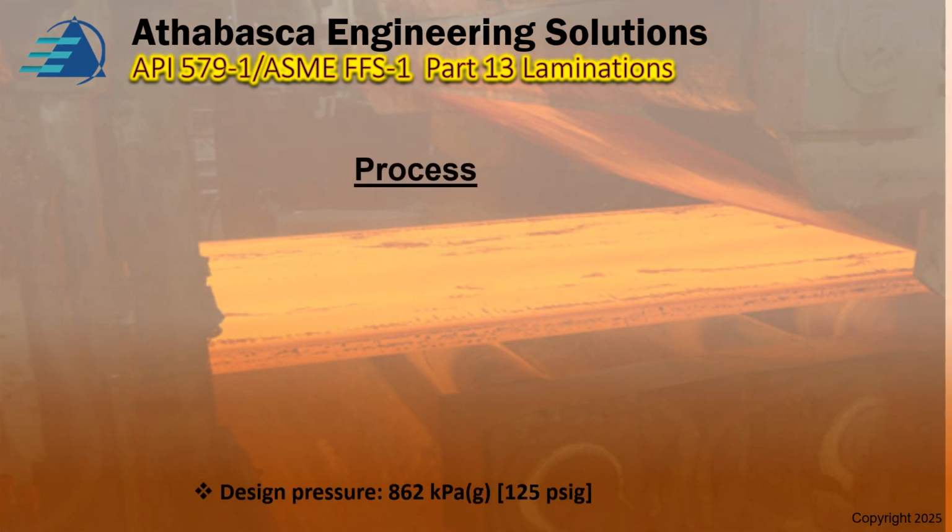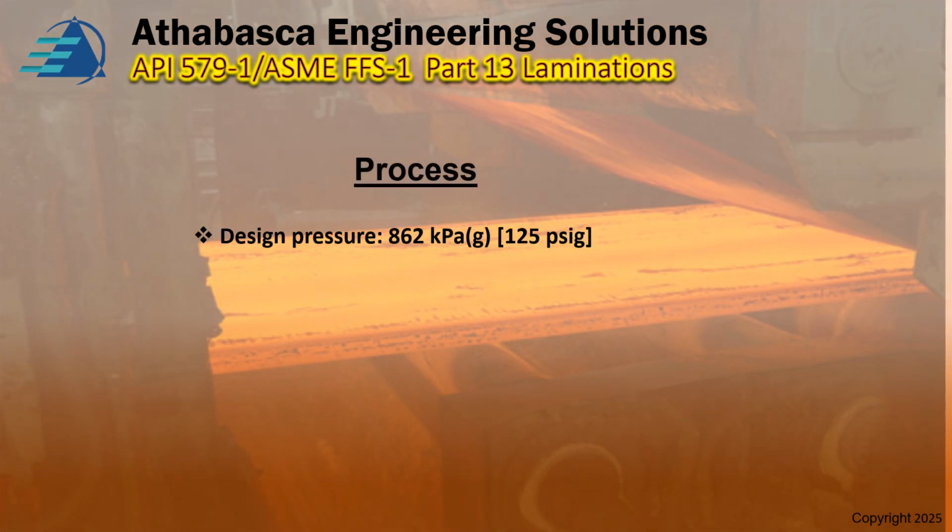The process discipline has indicated that the design pressure remains at 125 psig, or 862 kPa. We're working with that in this example, but oftentimes it could be lower.